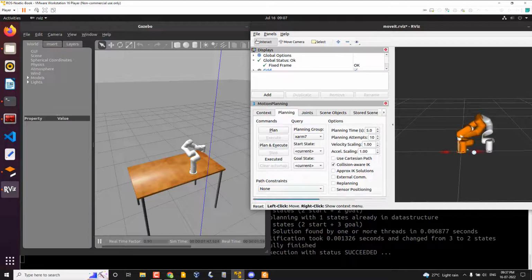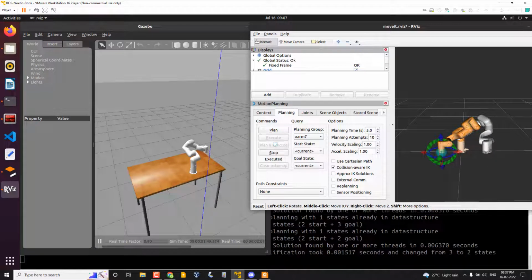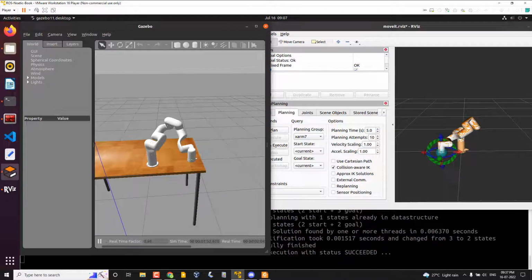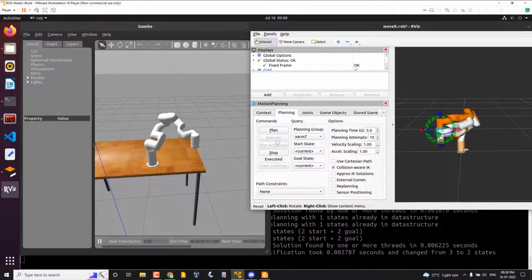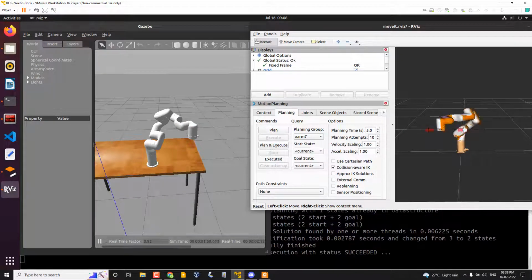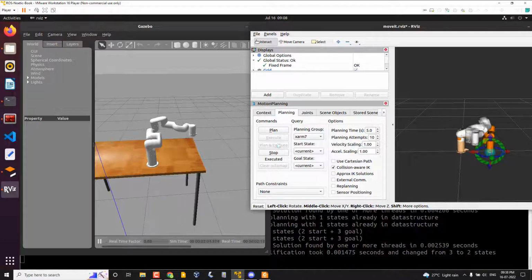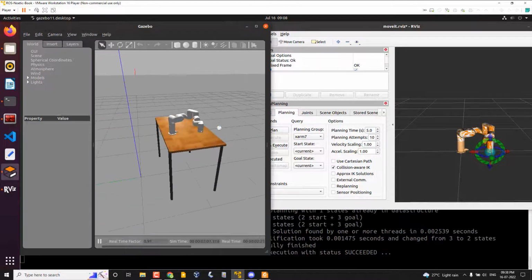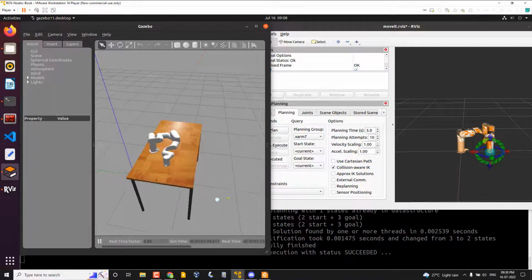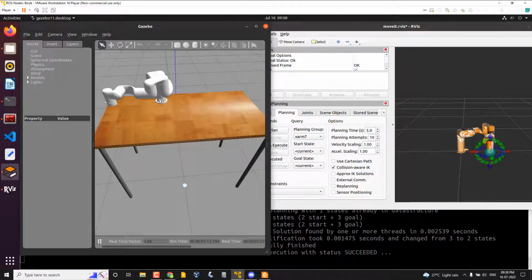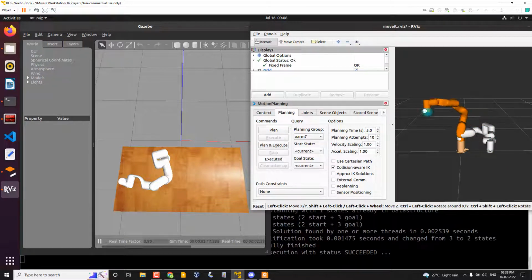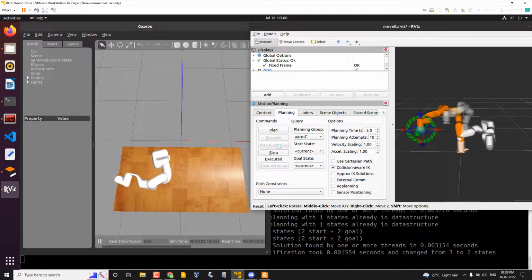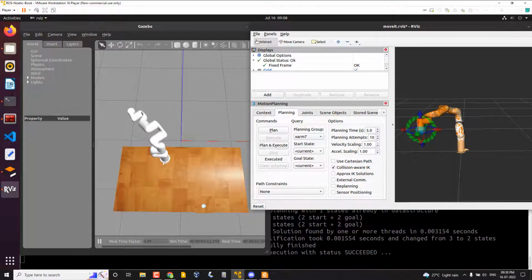Through this you can easily implement some kind of pick and place. I will not say this kind of planning is pretty accurate, but we are able to fine tune the motion planning and inverse kinematics solver parameters, so it will work. Yeah, it will work well. But I still have doubts regarding the repeatability, like the IK solution will not be available in all the positions.